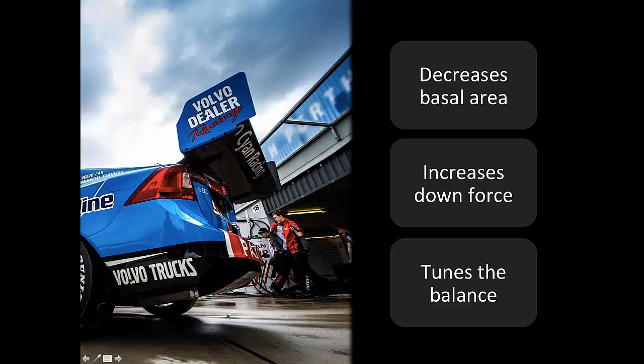With tuning the balance on a diffuser, generally diffusers in a lot of rule books I've seen, they generally limit the height of a diffuser. So you can play with things like departure angles and length. With the supercar it's a bit more difficult, and you'll see why in the next image. The silver mesh in there, that's actually the crash structure of the car, and then the yellow is the under tray or the cradle underneath the transaxle. So it's quite difficult to get a diffuser of any decent length in there.